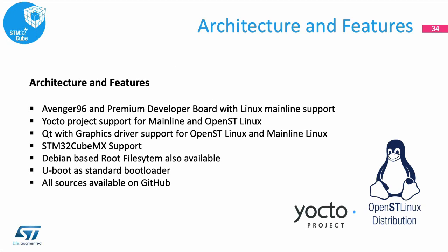On the next slide, I would like to explain in a fast way some main features of our software support for the computer on modules. First, as I told you, we support for both STM32MP1 based modules a mainline-based Linux version. This helps us in the further development and above all in the later maintenance of the BSPs for all projects. Then, for all board support packages, Yocto project is supported. The next point is Qt support. Note again, the GPU works also with our mainline version. Then, ST supports also STM32CubeMX for the MP1, so you can use the STM32 family tool for the MPU too.